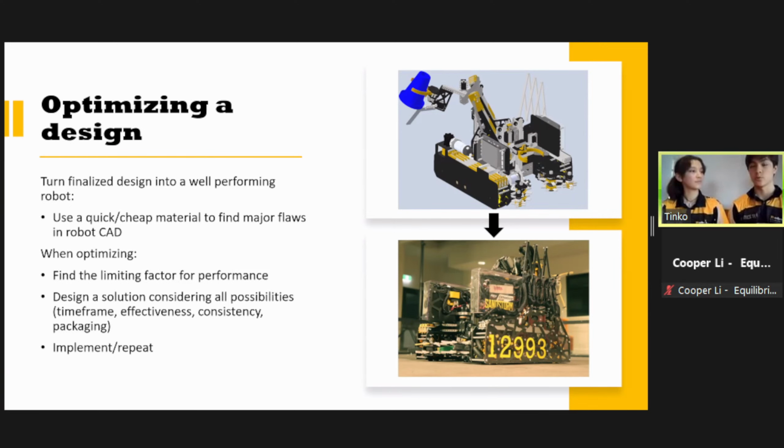That's always important to do. Then quickly test the subsystems, but don't spend too much time trying to perfect a robot with cheaper materials, especially if some of the plates need to be aluminium. After that, we move on to a more optimal material, for example aluminium, which has a better strength to weight ratio, which is better for robot play. Then we begin our iterating process from our first competition, since we might need aluminium parts for our robot to work.